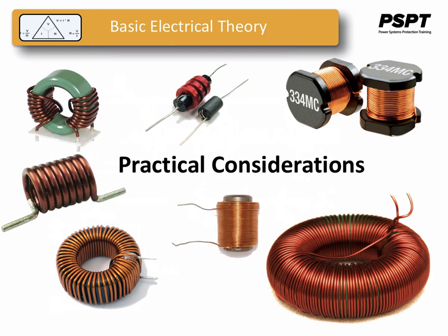Inductor size. Inductors tend to be much larger physically than capacitors are for storing equivalent amounts of energy. This is especially true considering the recent advances in electrolytic capacitor technology, allowing incredibly large capacitance values to be packed into a small package. If a circuit designer needs to store a large amount of energy in a small volume and has the freedom to choose either a capacitor or an inductor for the task, they will most likely choose a capacitor.